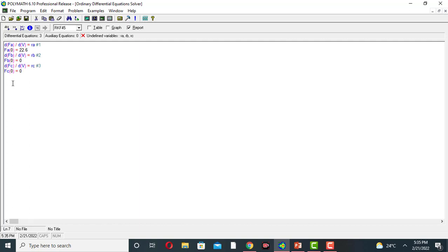Now enter the explicit equations. You can enter the explicit equation like the other value. Temperature was 698 Kelvin. Don't write the unit of temperature because you know that the temperature is in Kelvin. Similarly, write the Ct0 value: Ct0 is equal to P0 divided by RT.